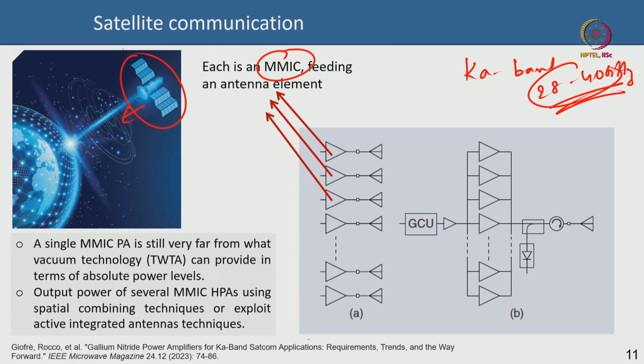It's too difficult, too challenging. So historically and even today the dominant technology that is used is actually the vacuum tube. Although we think vacuum tubes are gone, they are not actually gone. Satellites use vacuum tubes a lot for transmitting power, because to transmit power like 100 watts at 40 gigahertz you need a vacuum tube, maybe hundreds of watts, maybe a kilowatt. These vacuum tubes can go up to tens of kilowatts at higher frequencies like that. It's insane, it's crazy high. You cannot have semiconductor device technology at that level.